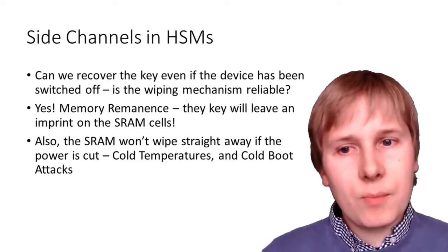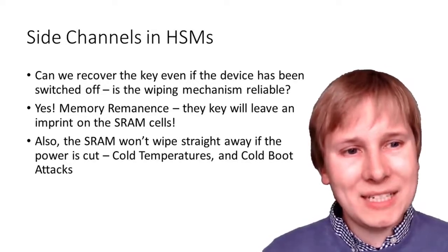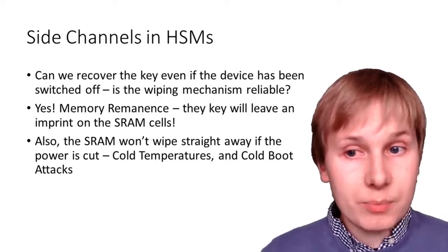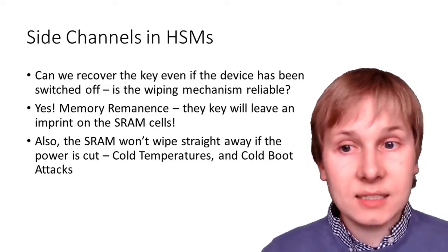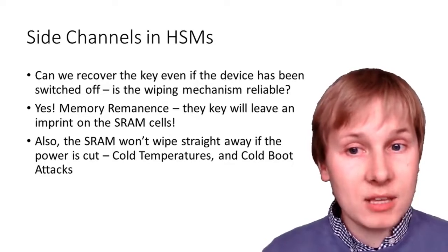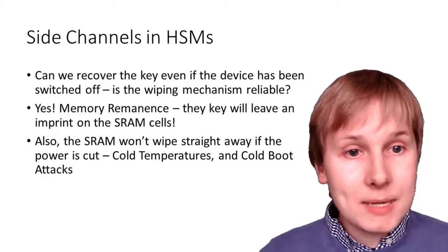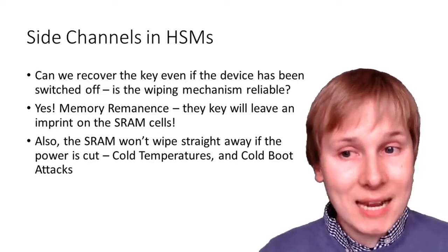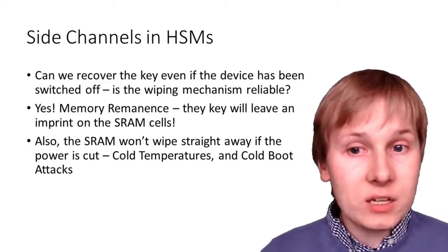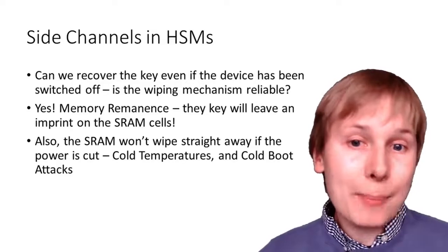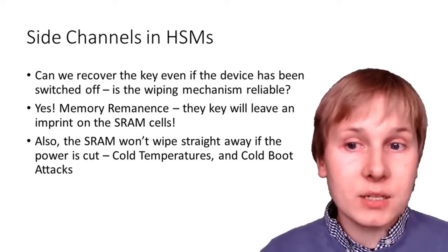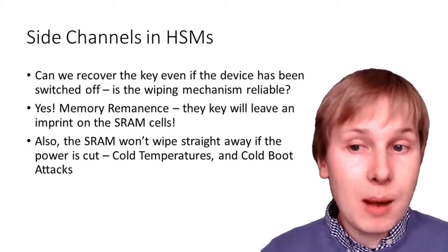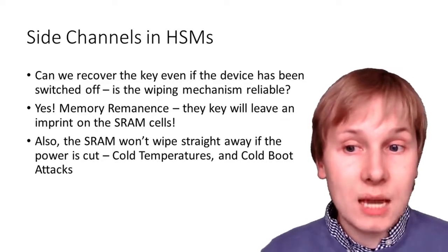Other problems come from systems not being as perfectly digital as you'd expect. SRAM, used for on-chip storage on computers, that has the same data in it for several years, ends up showing properties of what we call memory remnants. The key gets burnt into the SRAM bits, and so when the device is powered on, it just happens to assume most of the key bits rather than all zeros or random noise. You get similar effects with flash memory, even if it's been erased several times.